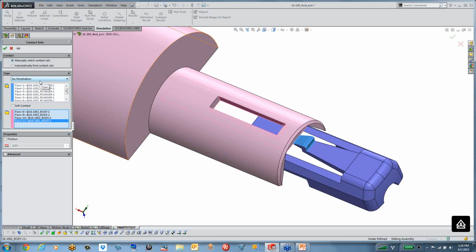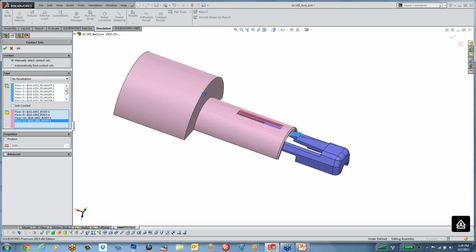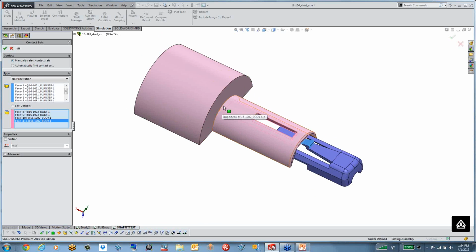And in this case, today's focus is no penetration contact. So you can see that when it comes to being able to define the no penetration contact, it's a simple geometry selection. You can include friction. So again, what we do is we simulate the Coulomb friction. So in case there's any kind of friction on surfaces, it's not really perfectly smooth, you want to include friction in your contact. You can do that as well.